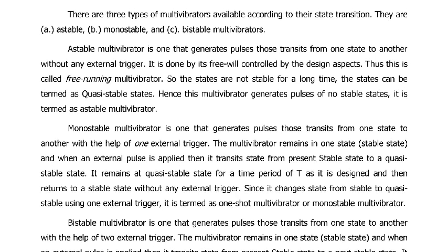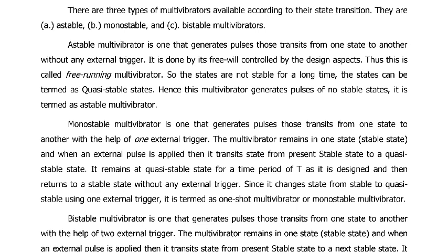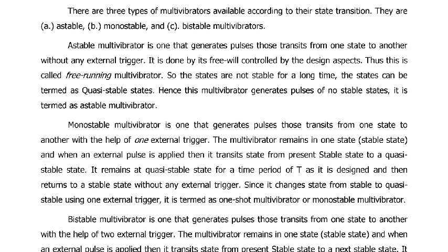Next is monostable. When an external pulse is applied, it transits from the present stable state to the quasi state. It remains in the quasi state for a designed time period t, then it returns to the stable state without any external triggering.